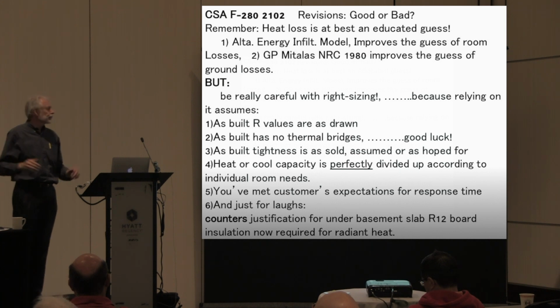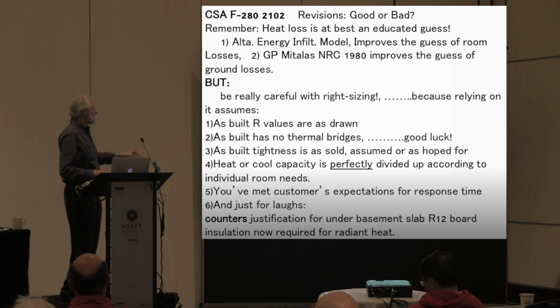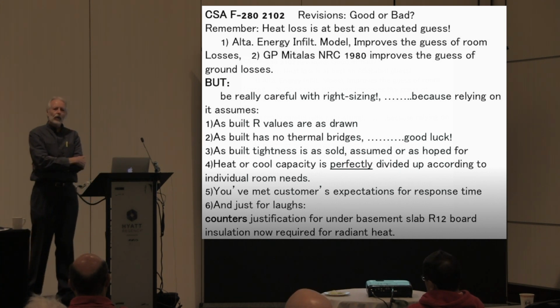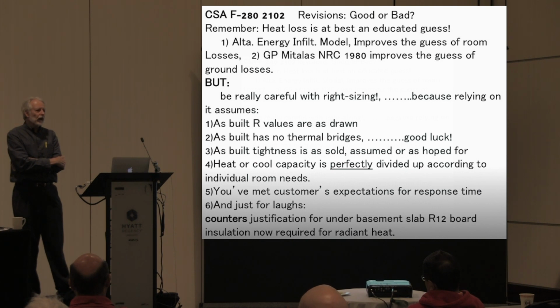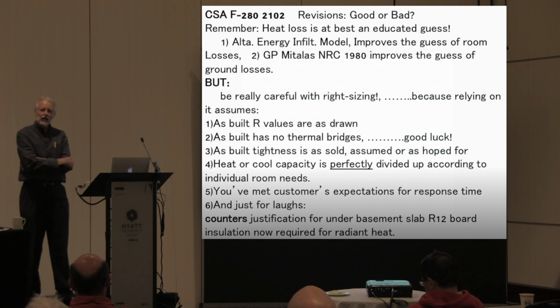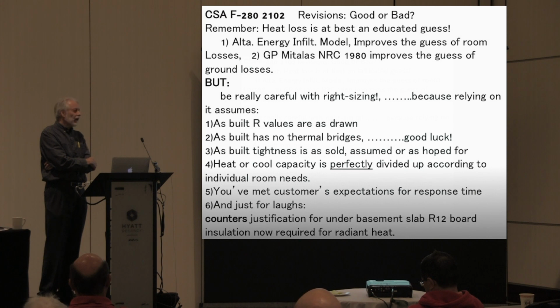Number 3, is the air tightness of your building what you sold or what you thought it was, or are you actually testing it? Because if you don't test it, it may be a hell of a lot leakier than what you think, because in the lower mainland, we get away with bloody murder here because our climate's mild enough. Mrs. Smith isn't quite as pissed as she'd be if you built the Vancouver house and tried to heat the sucker in Prince George.